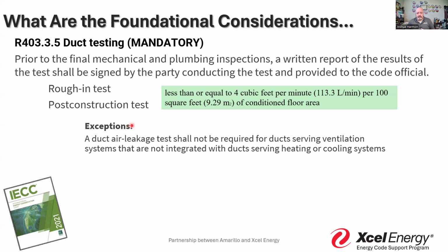What we're expecting is that as part of this process, we're evaluating how well those ducts are doing, right? We have a rough-in test, we have a post-construction test. We have duct testing to make sure that the duct is performing the way it's designed. Now, we know that we don't do duct testing when we're talking about ducts that are completely within the building thermal envelope.